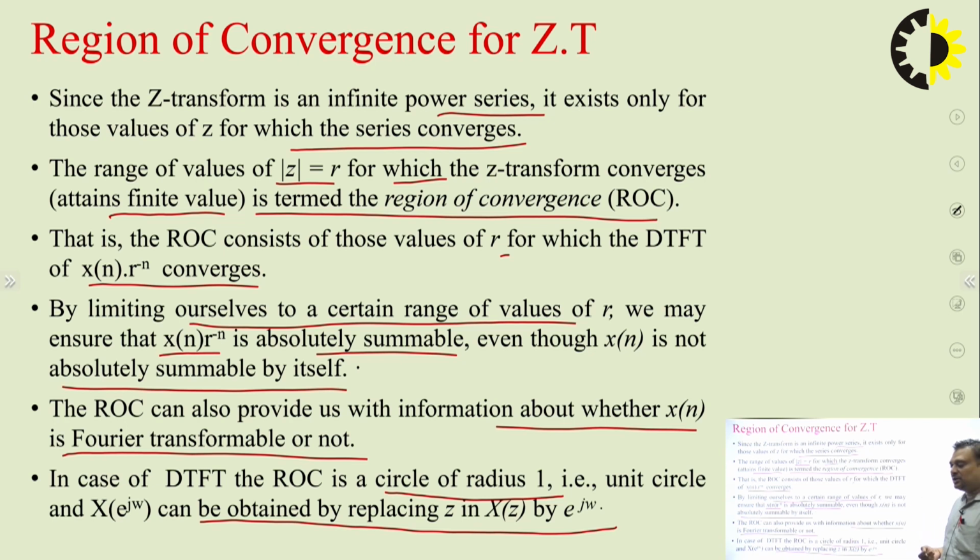or for which we are calculating Z transform, its ROC overlaps the circle of unit radius. If it is so, then that signal is also Fourier transformable. Okay, so what we have to do? We will calculate Z transform and simply put z equals e^jω in the equation to get the DTFT for that signal.